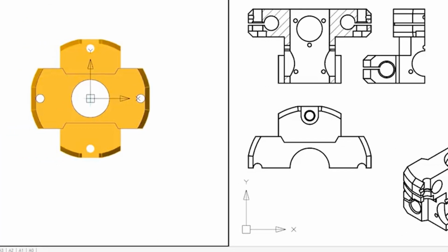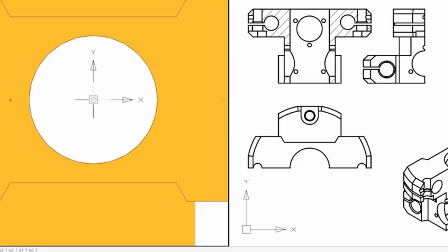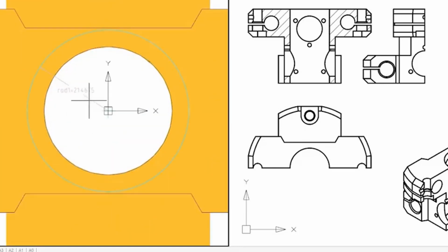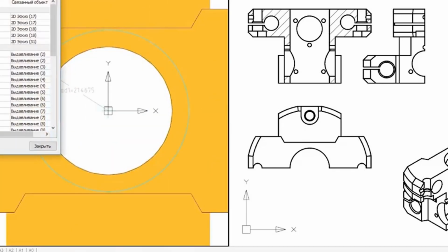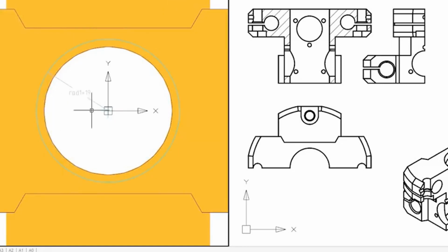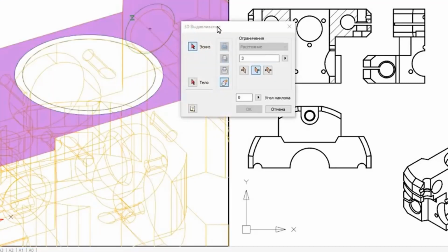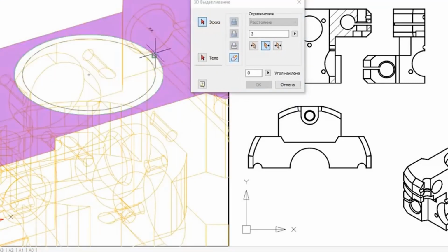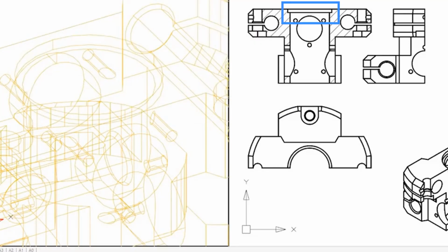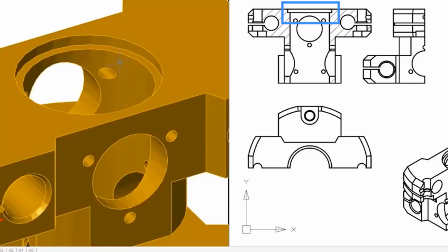You can use nanoCAD Pro's 2D drawing tool to select any face on which to draw. Here we draw a circle, setting the size as a parameter. A sketch outline appears on the upper part. Let's move to using three-dimensional modeling tools to extrude a facet by 3 millimeters. Changes show up simultaneously on the 3D part and the 2D sketch. Works the other way too. Here we make a chamfer on the 3D part to immediately see the change in the 2D drawing.